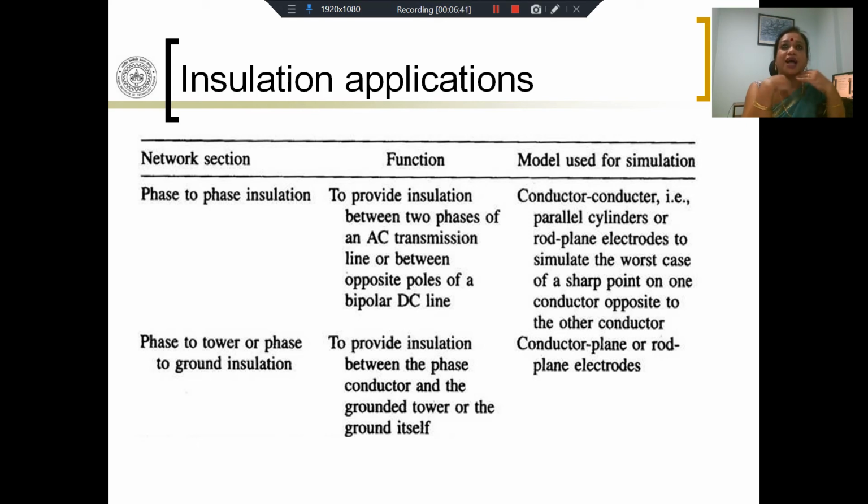Sometimes, if there is adequate enough charge production, it may so happen that the mechanism will start as a Townsend mechanism, but will give over to the streamer mechanism, in which case photoionization is involved, and therefore the breakdown will progress much faster than we predict through the Townsend mechanism. It also explains the zigzag lines that you see in a discharge, which cannot be explained using the Townsend mechanism. Townsend's mechanism and streamer mechanism are both relevant to breakdown in uniform fields.